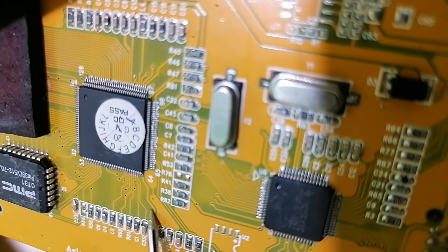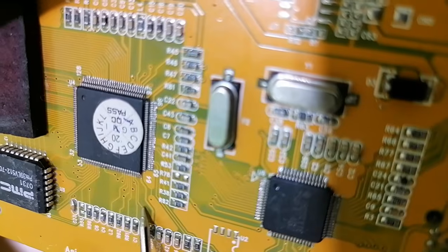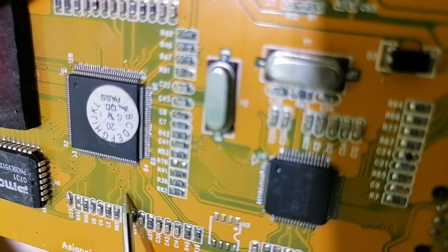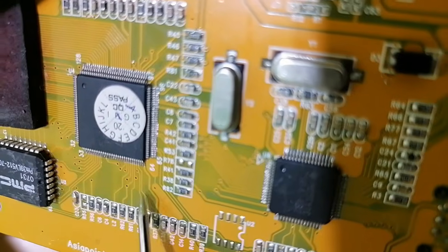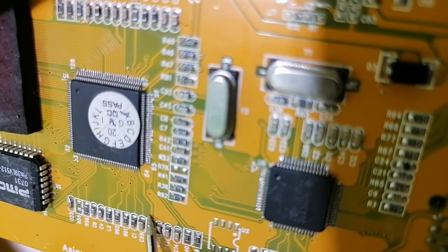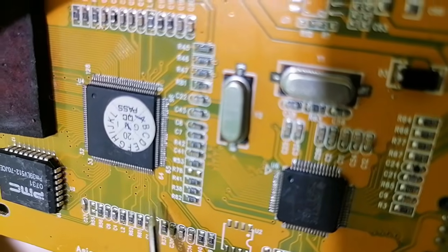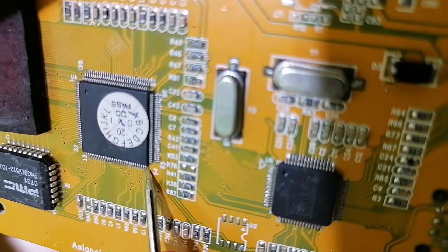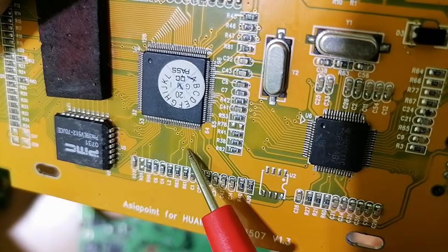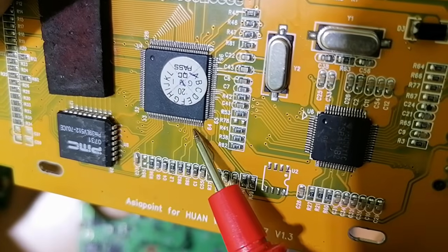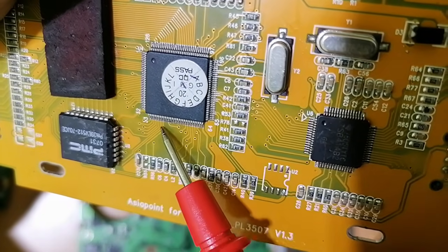So I want to share with you here a very important tip. If you focus here, as you can see, we have this path over here, these lines. Do you see? These lines basically are not the same as this one. So this is a bolded line. This bolded line means here we have power. Here we have VCC. And those lines, as you can see here, thin lines, means this is just control signals.